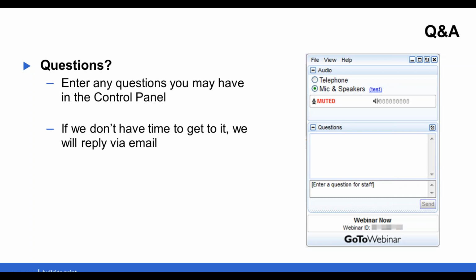Another question here is, can ABS be used instead of aluminum in faceplates and bezels? Yes, absolutely it can. ABS is a great thermoplastic, but it has some drawbacks. It can be susceptible to UV and certain solvents, but assuming that the bezel is non-load bearing and is mounted sufficiently so that it won't go into resonance during vibe, it's definitely worth considering as a material instead of 6061 aluminum, which is what I'm assuming.